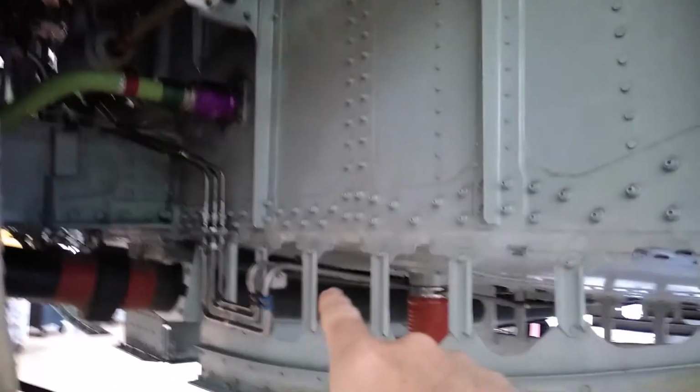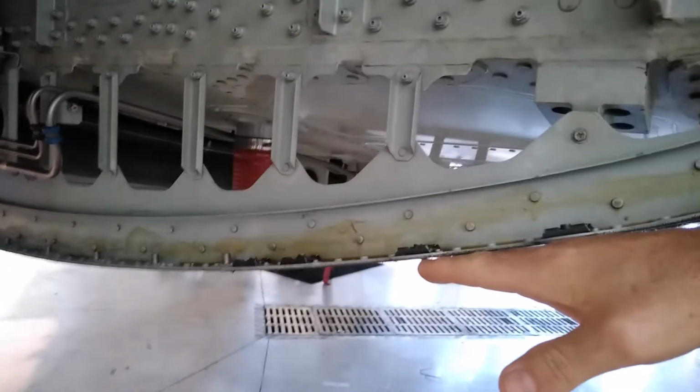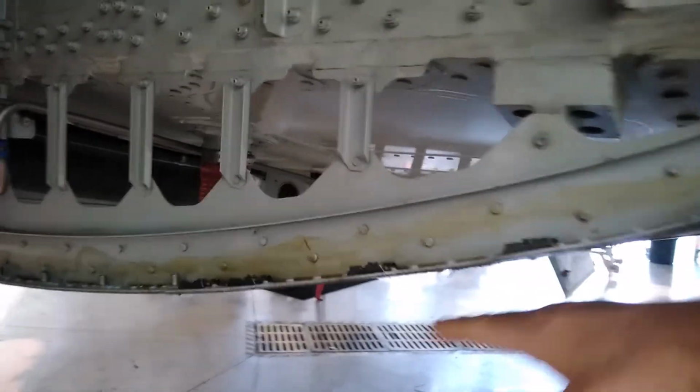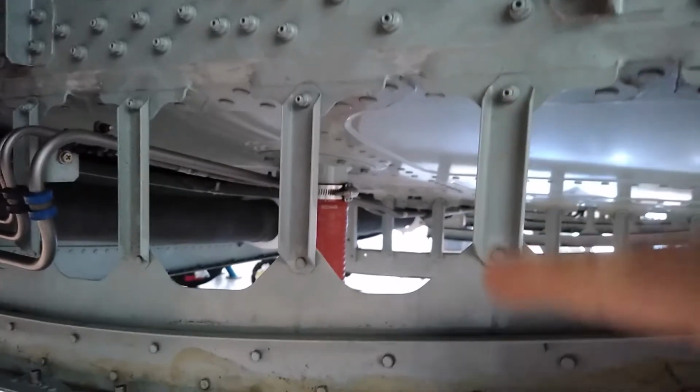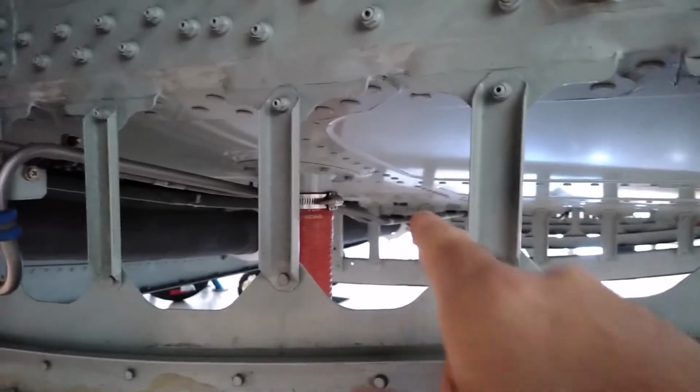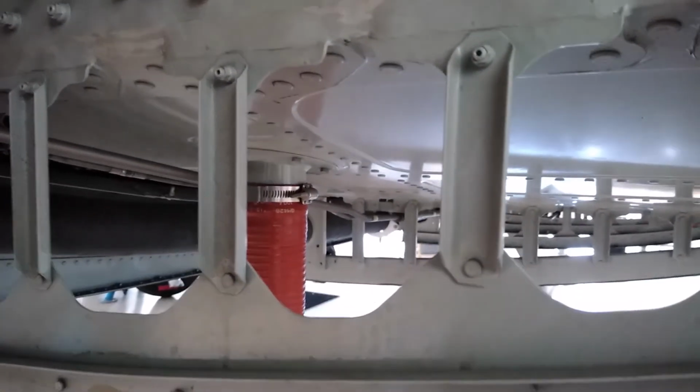Ultimately, that air that leaves the cabin through the outflow valve flows in through this area, which below here is a fairing, which closes all this in to keep it smooth. So all that air blows in between the bottom of the wing and that fairing and goes out to the aft equipment bay, and that's where we're going now.